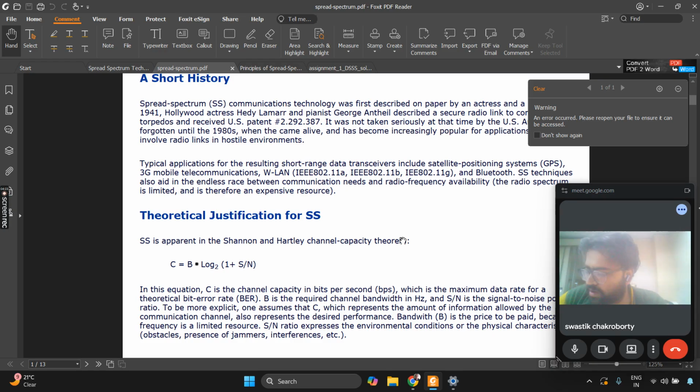If one user has a particular message, another user's message can also be added with that, and they can be decoded separately. Only the intended user will receive the actual contents of the message. For the other person it will be like noise. It allows multiple users to transmit in the same radio band, and this technology is called code division multiple access.